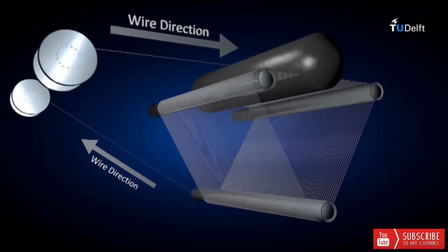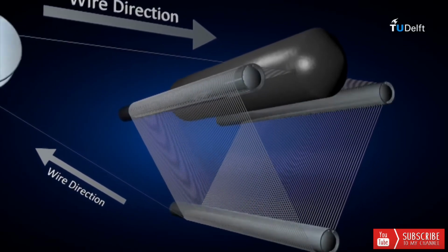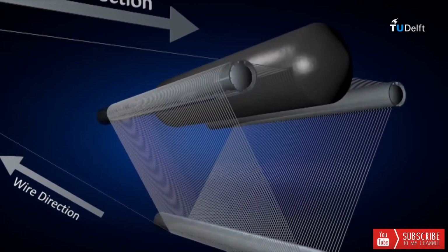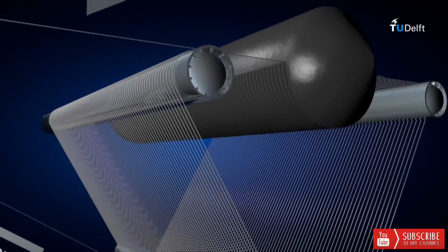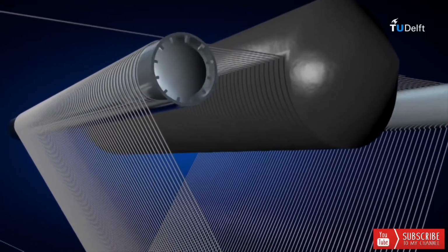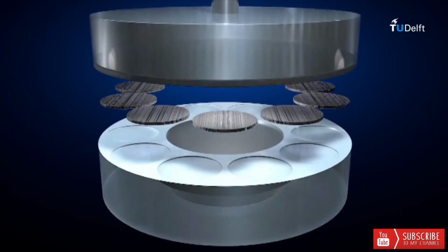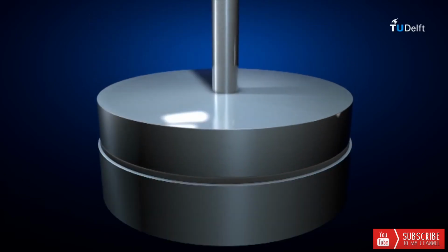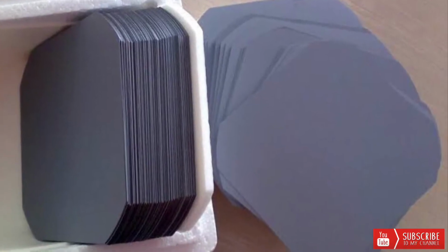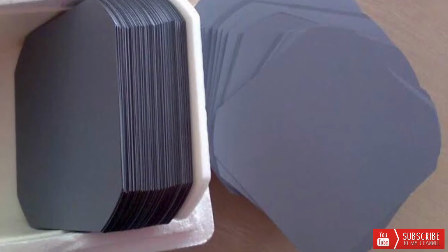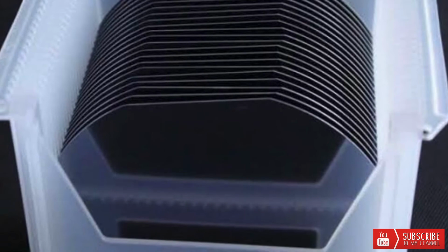The next step is wafer manufacturing. The silicon ingot is sliced into thin discs, or we call it wafers. A wire saw is used for precision cutting. The thickness of a wafer is similar to that of a piece of paper. The optimum use of this expensive monocrystalline silicon demands, instead of slicing it into a square which could be inscribed in a diameter of ingot, to make them slightly larger, a rectangle with chamfered corners. That way, we waste less of the material in cutoffs.